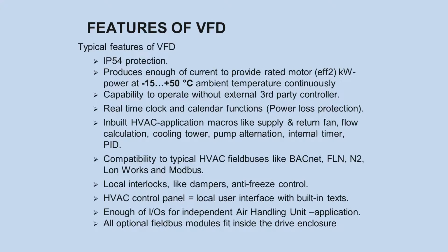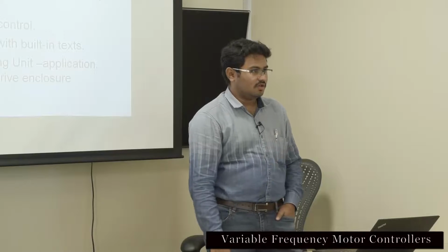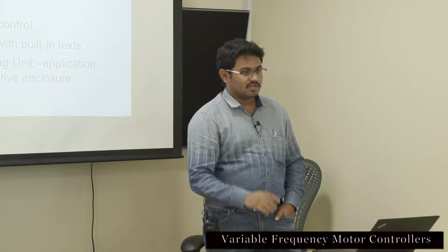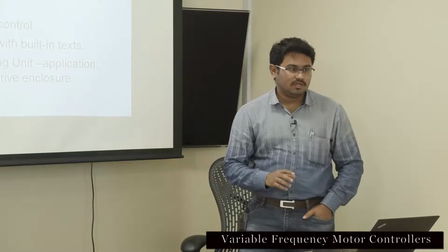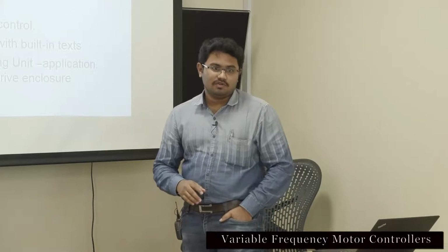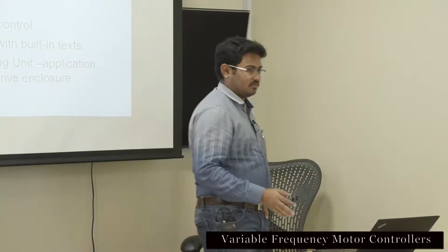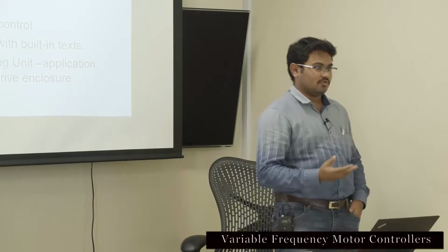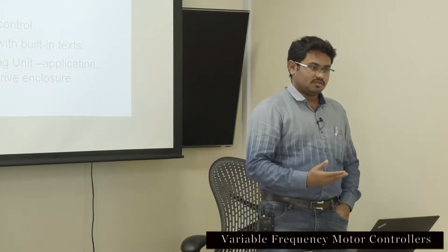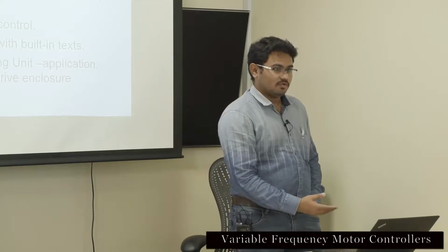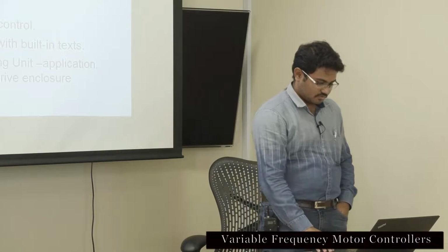On the compatibility of the drive with communication protocols, at least with the ACH550 drive, we have Modbus and BACnet communications, which are default on board. And with the ACS800, we can use the adapter module, which is RMBA for Modbus, and it supports almost all the protocols available in the industry, because as it is an industrial drive, it has to support all the communication protocols. And in MTB, we are using the Modbus communication for monitoring purposes.